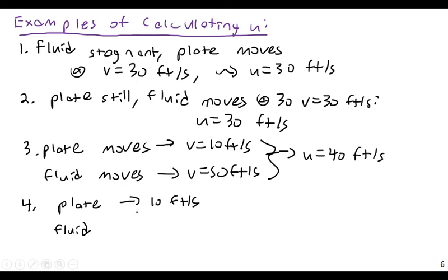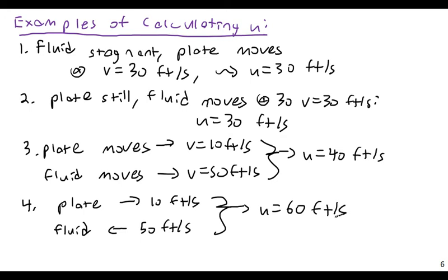So the same ideas of drag and lift can be applied to a watercraft, as they often are. And so we'll have a plate moving at 10 feet per second to the right, and a fluid moving at 50 feet per second to the left. And this comes together to produce a relative velocity U equal 60 feet per second. So again, it is the relative velocity that we'll use when calculating drag.